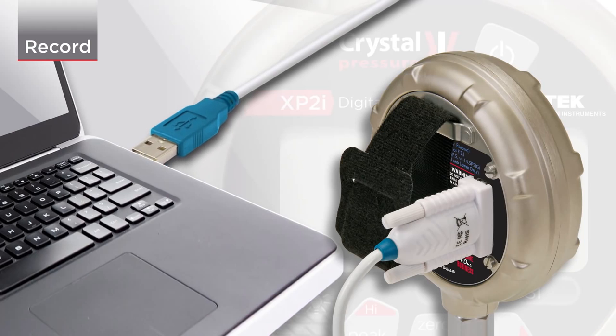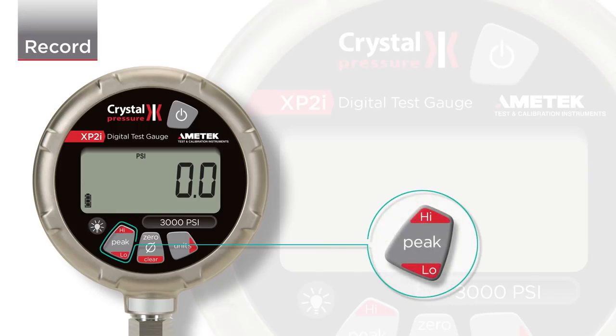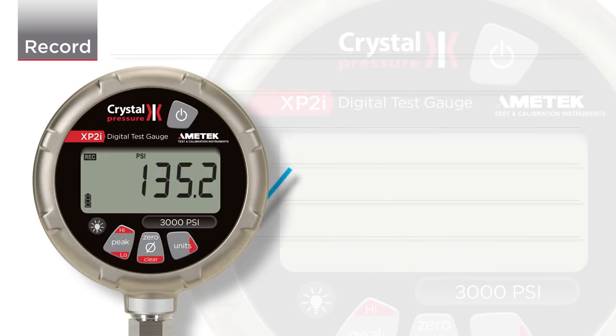Before you begin a recording, you need to ensure that you are in recording mode. In order to switch to recording mode, press the peak button repeatedly until the REC icon illuminates. Then press and hold the Units button to begin recording. First, you'll see the current state of the recording run. Then, the number of available points left on the gauge for recording. Then you will see the word Start. When you see the word Start, the recording begins.